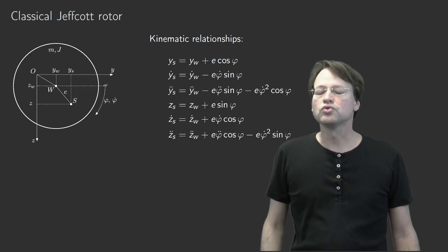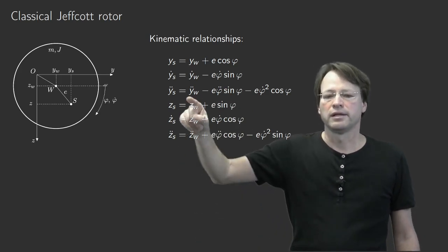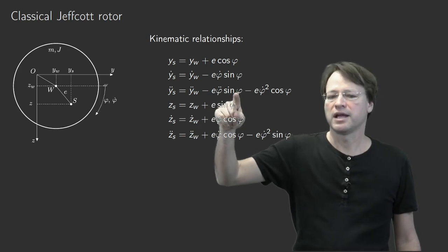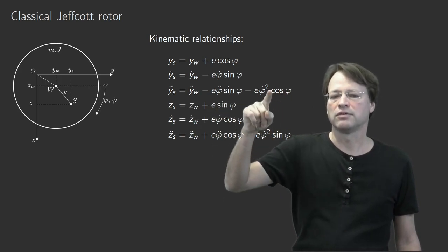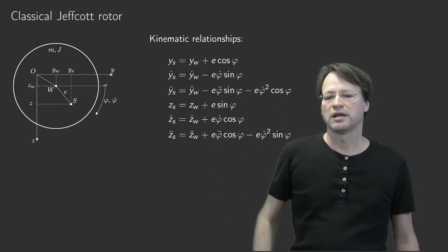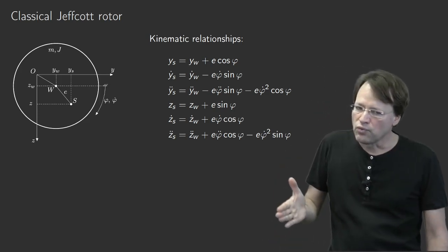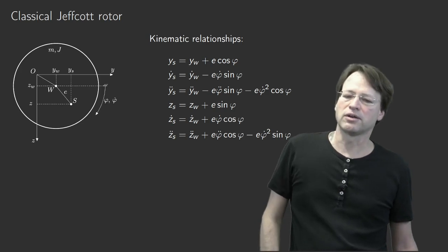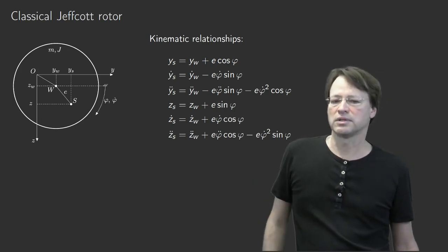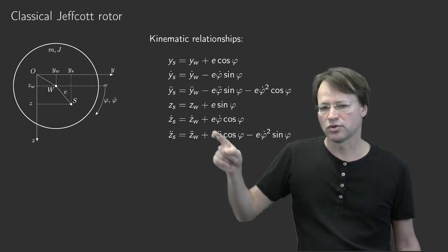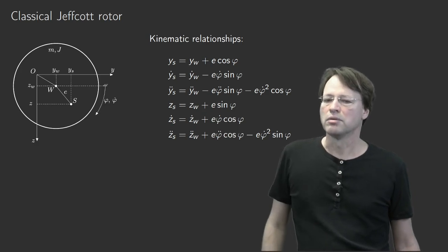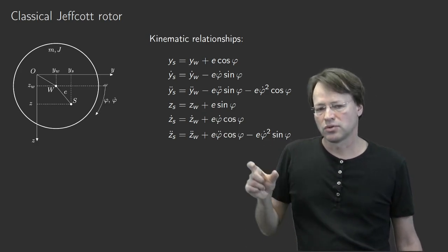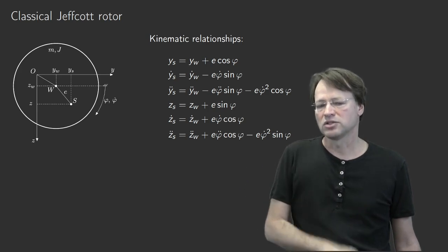These additional terms do not depend on the coordinates of point W, but they depend on the angle phi, on the angular velocity, and on the angular accelerations. So I will move all these terms to the right hand side of my equation of motion, and on the left hand side I just will keep the inertia term relating now to point W. I will keep the restoring forces, so the damping term and the stiffness term.